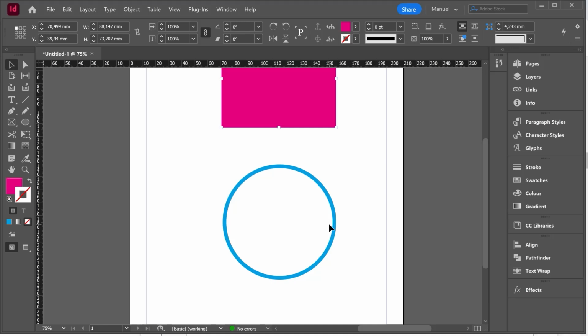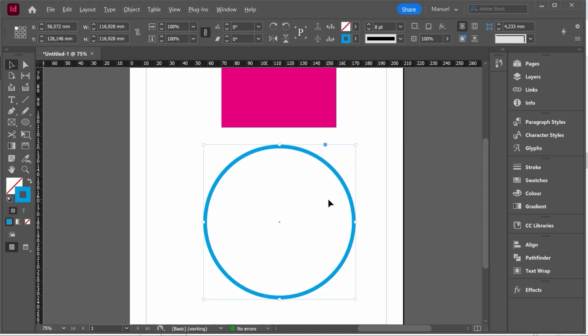Then we have to use a little bit more sophisticated combination. I select my geometry, I click and drag from one corner, and then I hold Shift key as before, plus Alt key as well. Then I drag and I can choose the new size of my geometry, keeping the proportions and the center. Then I release first the mouse, then Shift and Alt key, and here we are.